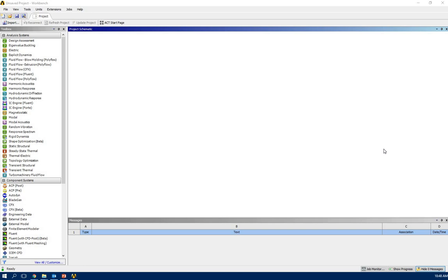This time I'm going to add a heater under our heatsink, so basically adding a heat flux boundary condition to the bottom of the heatsink, and see what is going to happen instead of having an initial temperature, but still it is going to be natural convection cooling.